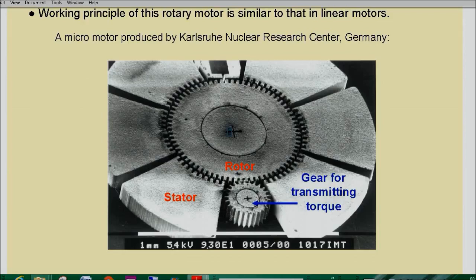So for such applications you can have this, but one problem that exists is this bearing. This is all physically connected, and there will be bearing wear and tear, and lubrication needs to be done. If you are driving a two-wheeler and your bearing is gone, your two-wheeler handle will start rotating, which is called wobbling.